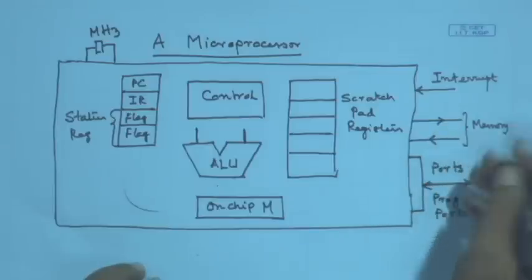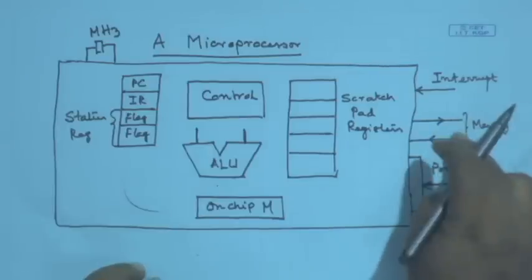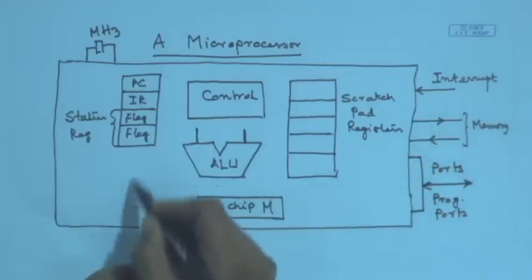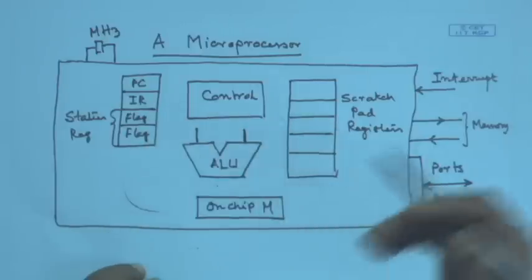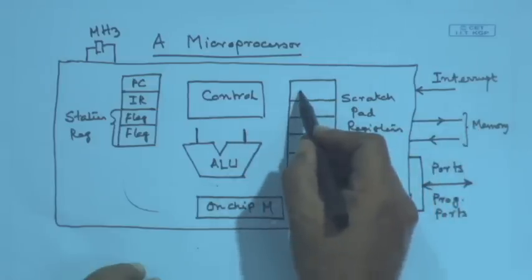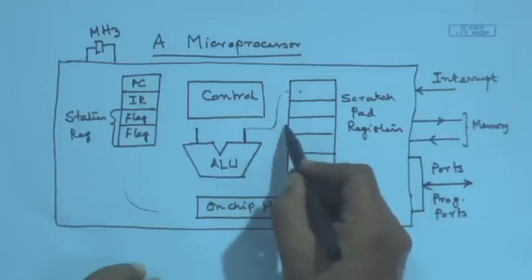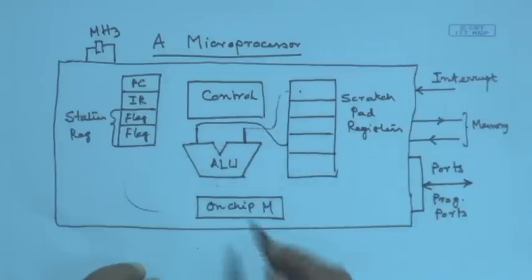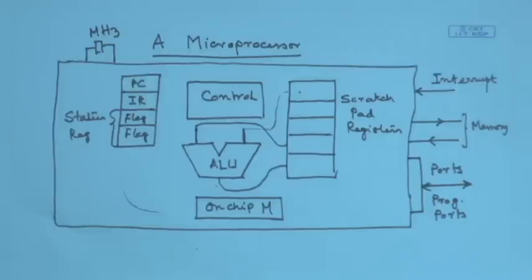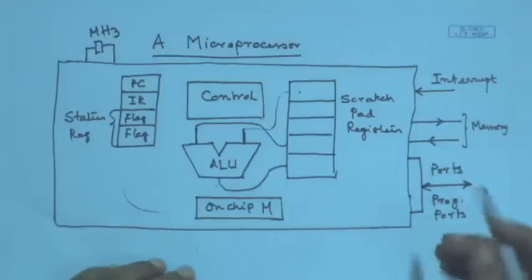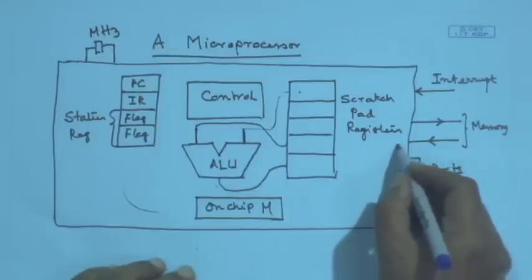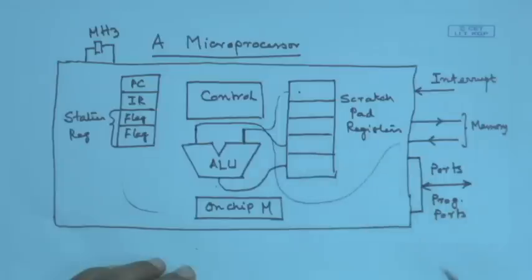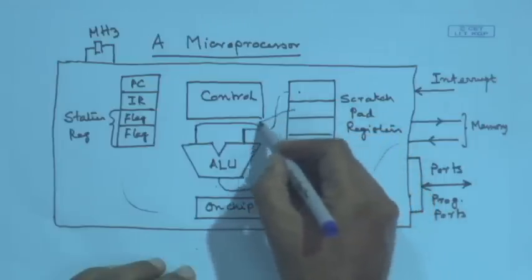And the data that was coming, suppose I fetch the instruction from the memory. So, there must be a data path that will bring it here. Say in one instruction, I want to fetch the data from two registers, this one and this one, and do the ALU activity, and the result will go here. That is one scenario. Now, in another scenario, maybe the instruction that is being executed is taking data from the memory and it is coming here. Another one is coming from this register here.